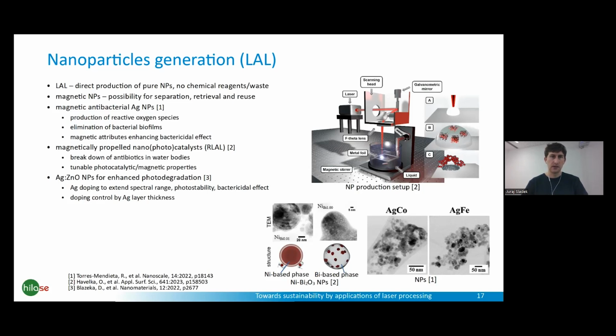We bring the laser beam and focus it onto the material we want to ablate in a liquid environment. Plasma is generated, then there is a cavitation bubble with the ablation products, and when the cavitation bubble collapses, the particles are ejected into the volume. Often this is done, or in the examples below it's done, with nanosecond lasers at low repetition rate, so it doesn't have to be any very special laser.